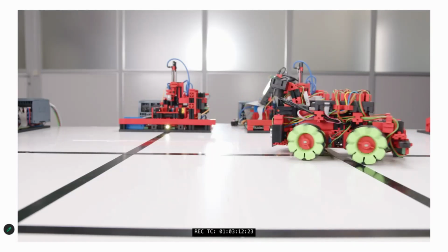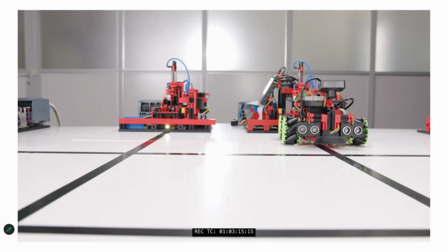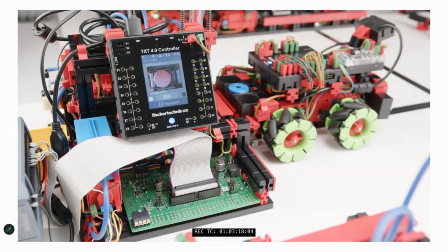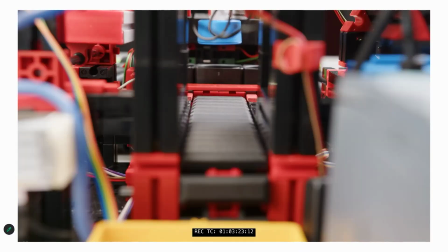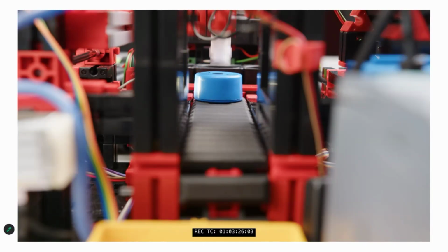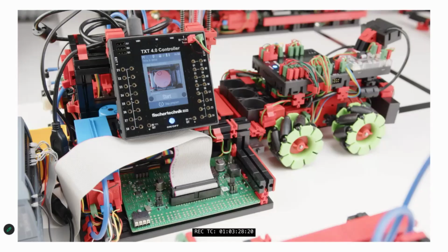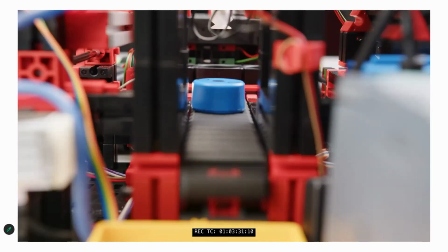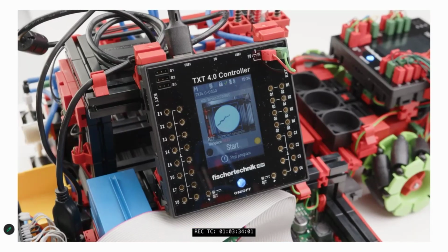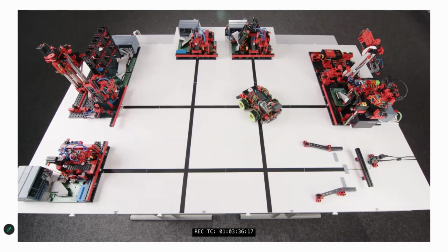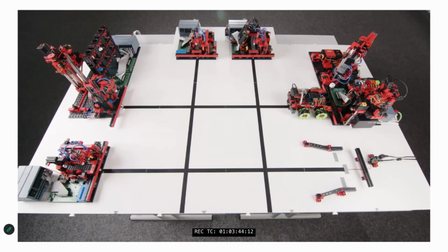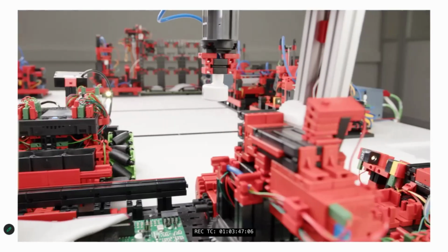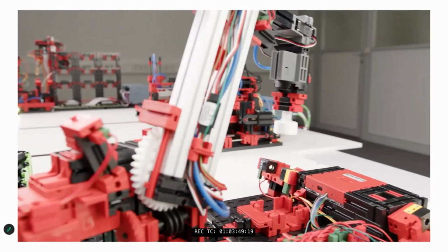Again, the workpiece continues its travels through the factory. Here it is going to the color sorting with AI. Again, the piece is picked up by the vacuum gripper here, put onto the conveyor belt, scanned by the camera. The AI detects the quality of the piece, whether it's a good piece or a defective piece. If it's a defective piece, it's of course rejected. Otherwise, it goes back onto the vehicle for transport to whether it be another station or the end point, which again is the same as the entry point.